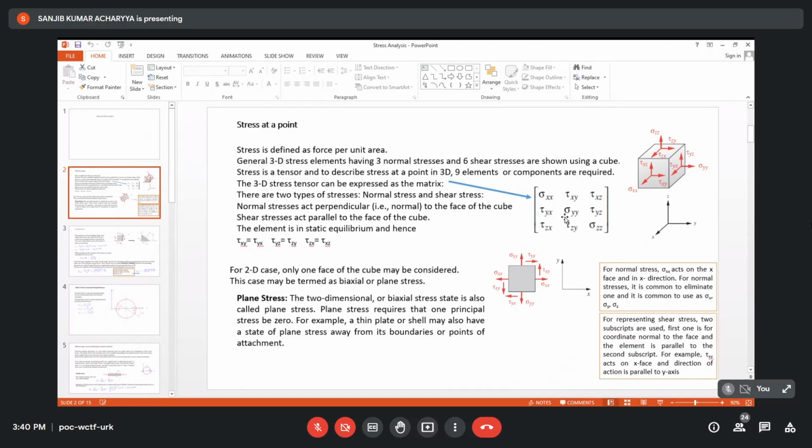All these 6 independent components are there in the member due to certain type of loading. Something is generated from bending, something from normal, something from torque. Means, sir, all are present. Suppose all are present. Even that will not make me confused, because I have expression in terms of sigma xx, sigma yy, sigma zz, tau xy, tau yz, tau zx. I have expression available in the book for principal stresses. Do you agree or not?